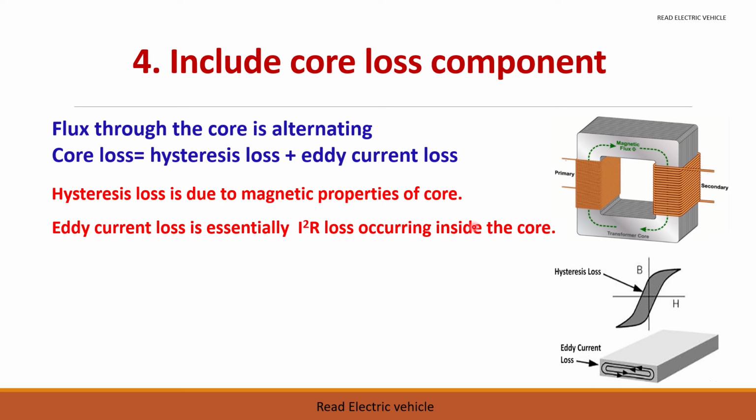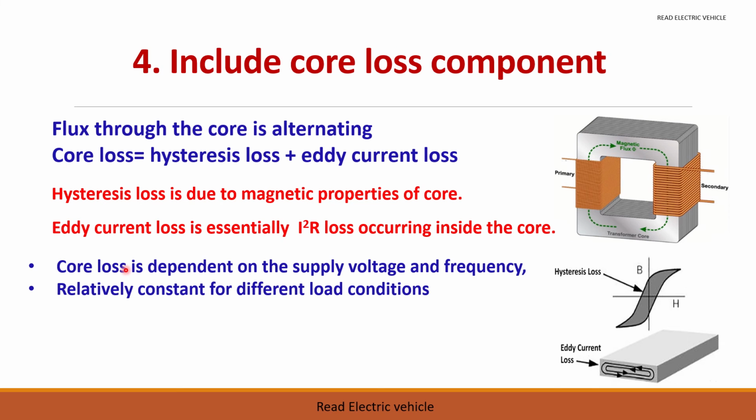We will talk about the losses separately. So we have two types of losses. This core loss is actually dependent upon the supply voltage and the frequency. As our supply voltage and frequency are almost constant, the core loss is assumed to be constant for different load conditions.